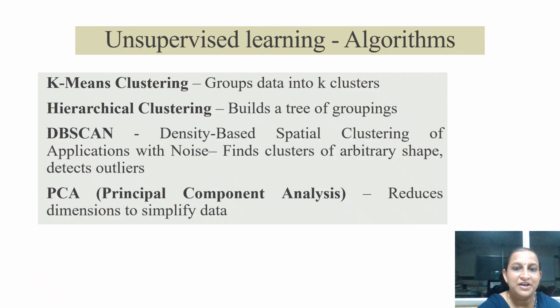And the unsupervised learning algorithms which are available include k-means clustering. K-means clustering is used to group similar structural data into k groups. In structural engineering, we often use large data collected from sensors, and the data involves measurements of strain, acceleration or displacement readings. This method groups similar structural response patterns and will be able to identify different behavior zones in a structure.